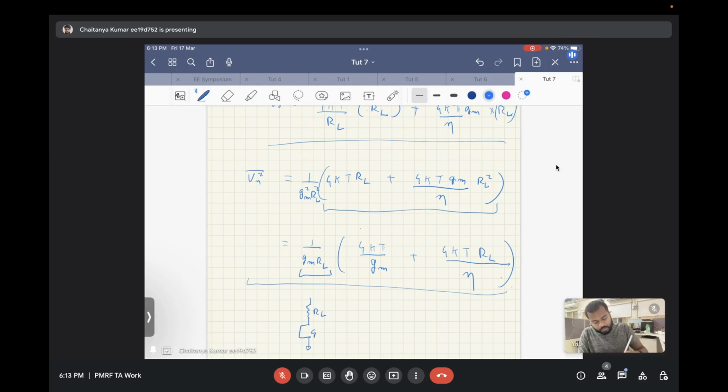So we have this common source amplifier that has a Gm block and a VD. Let's say you are given a top level spec that you need a gain of 4 from this amplifier. Now a gain of 4 can be achieved by multiple combinations of Gm and RL, but you need to see what values of Gm and RL you should choose, because the noise after the amplification will be different in both cases, correct?